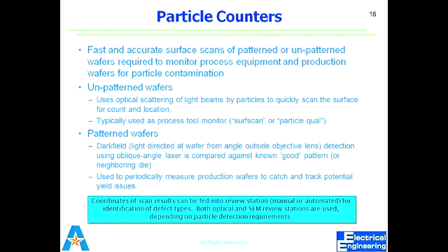And if you have a patterned wafer, in that case, patterned wafer means you already have a rough surface. You don't have a smooth surface. So when you already have a rough surface, the phenomenon of hitting vertically with the laser, and after that expecting it back at a right angle, will not work for a rough surface, because the rough surface means that it will never come back vertically. So even if it's the pattern, not the contamination, you will feel like there are particles and contamination all over the surface. So you need to go for another technique for the patterned surface or the rough surface.